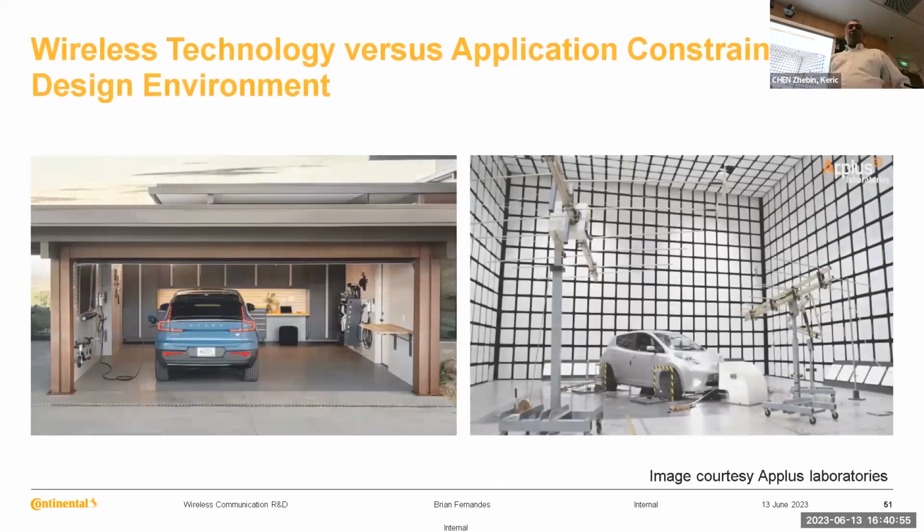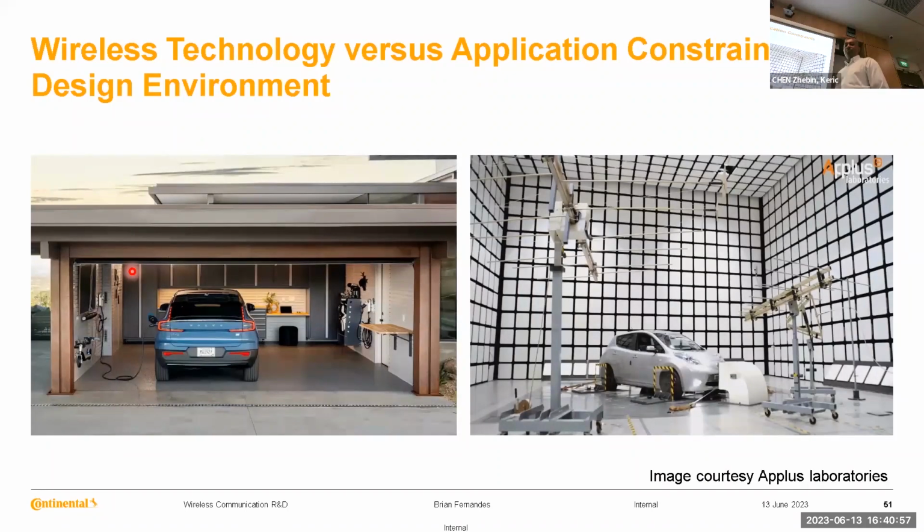Similarly, you also have a constraint: as designers, we want to design our product in a good, pristine environment that ensures that there are no variable noise sources coming in and going out, and we want to ensure there are no reflections in our system. So for example, you use an EMC chamber or an anechoic chamber to do your product development.